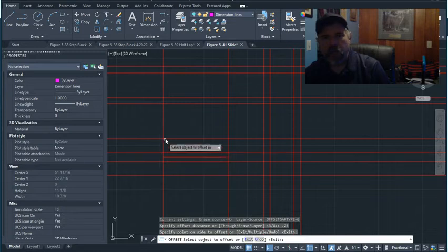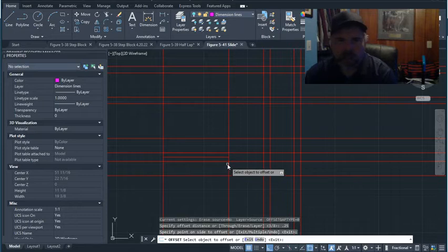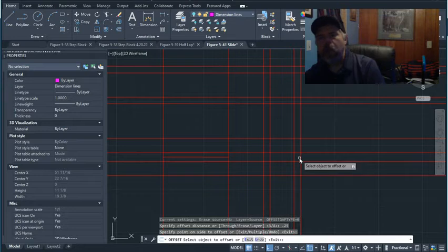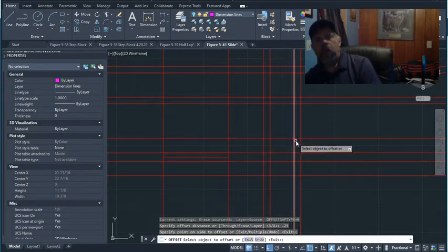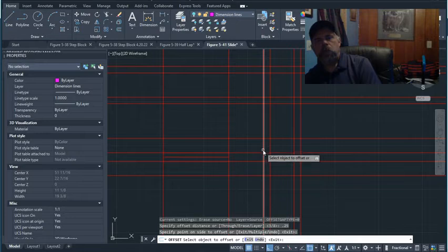That gives me my block shape of my front side. Then I'll set this line over 2 inches, and then again 2 1/8. I'll set this line inside 3/8 of an inch because I know this slot is 3/8 of an inch deep.